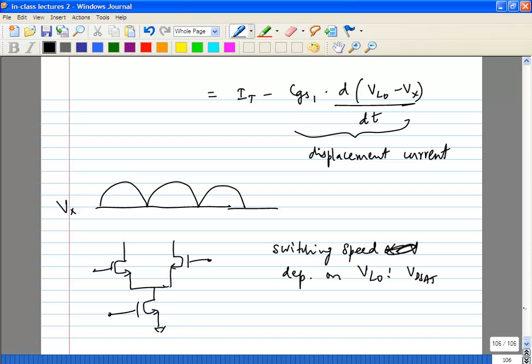But the one thing to remember, you always have some parasitic capacitance at this common node. So your lower overdrive, you can get it in two ways. One way, increase the size of M1 and M2, which means CP increases.